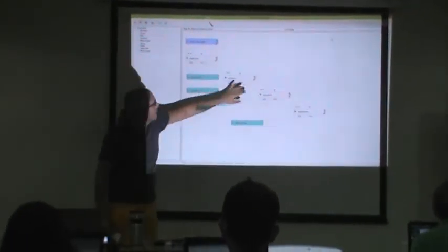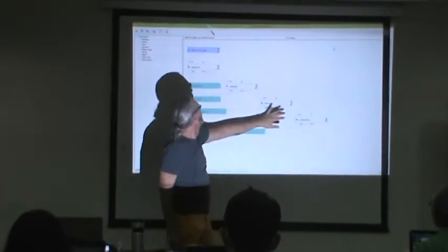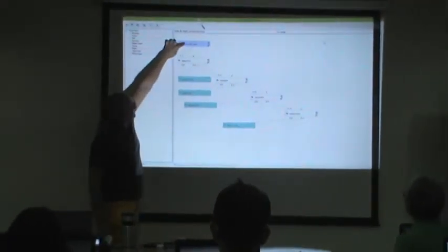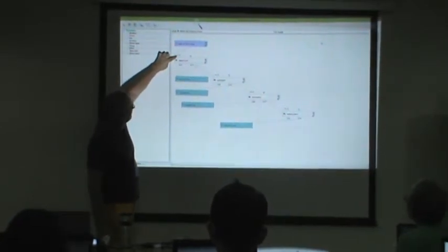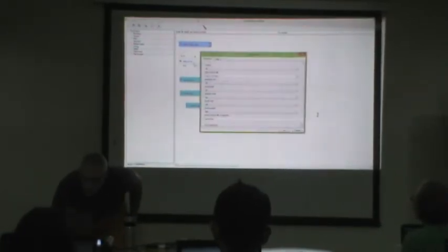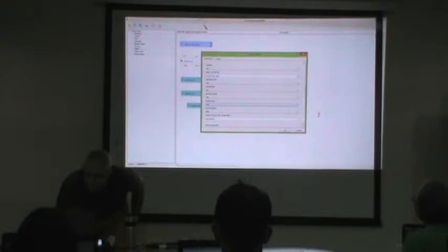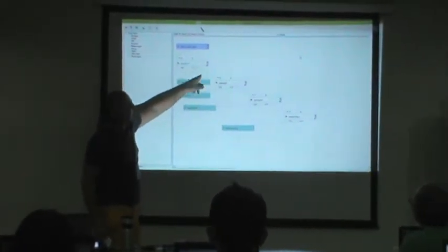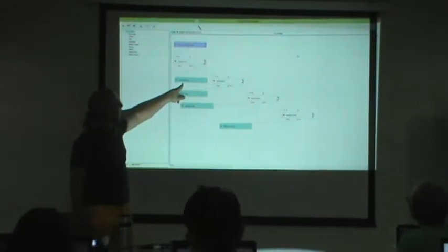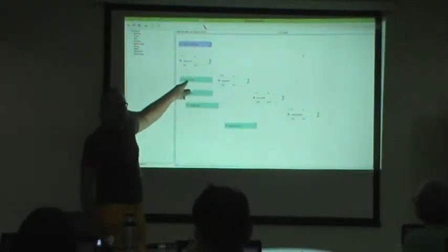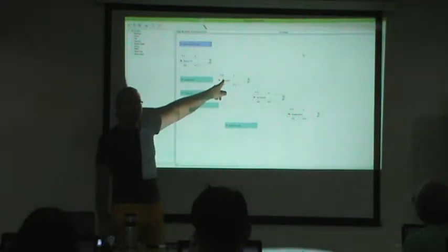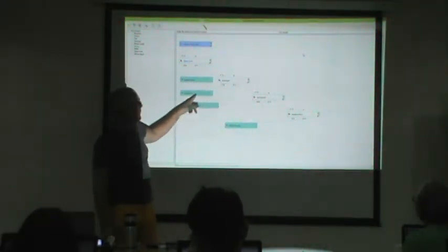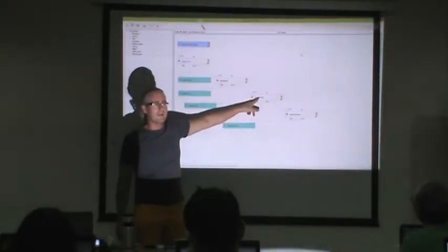So I can now take my individual LAStools and I can say use this as input and then run lasground. And then you can go into lasground and you can set the options. I set the option to city and fine and so on. And then I can say this produces this file. And this file is A, saved, and B, I want to use it as input to lasheight. And then I produce this file, and I want to use that as input to lasclassify.